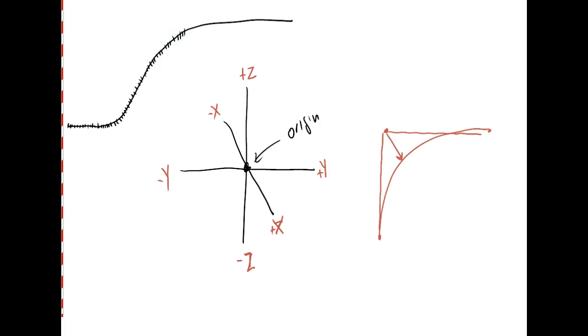That makes sense? What a point-to-point robot would do is I would have to come up here and teach that point. I'd probably teach a point right there. I would teach a point right here. And this might be a circular move. This might be a linear move. This right here might be a circular move.